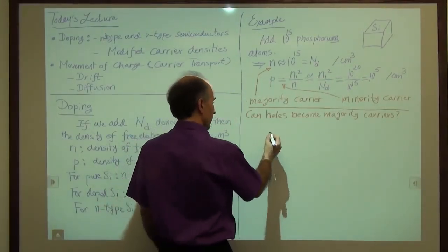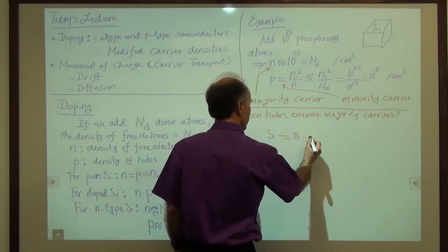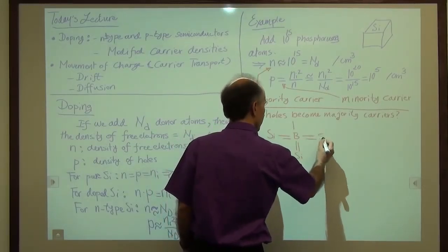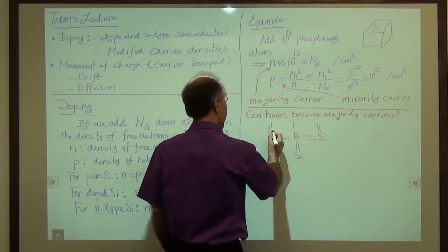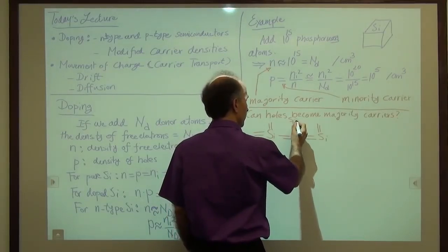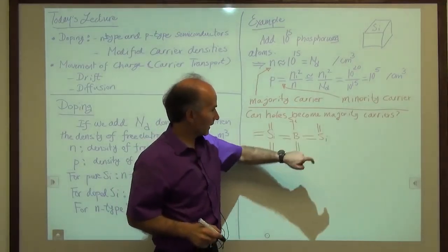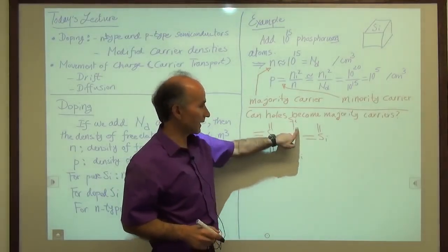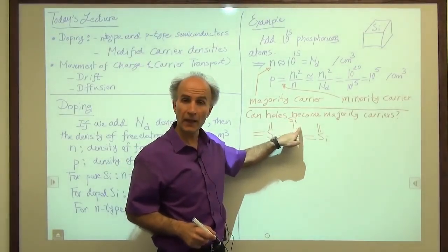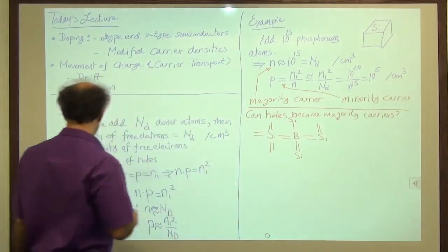Okay, well, we will form a crystal of silicon, but this time we introduce boron atoms in there. Now boron has only 3 electrons in its last orbital, so it cannot form a complete bond with the neighboring silicon atom. So it will end up using one electron with this, one electron with this, one electron with this, but doesn't have another electron for this silicon atom. So there will be a void here, and that void is a hole because that bond is not completed. So we end up with a hole here.